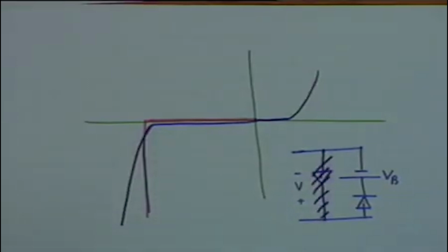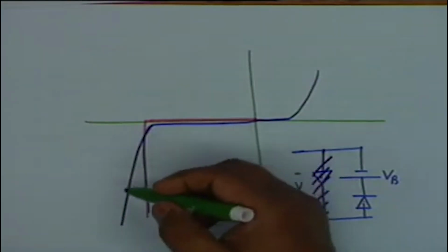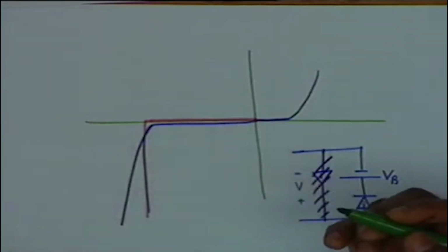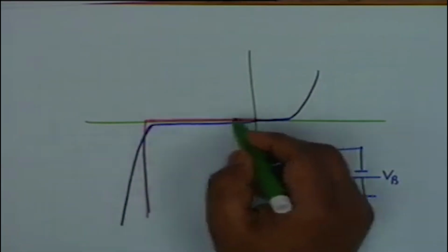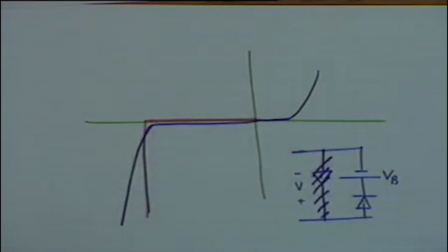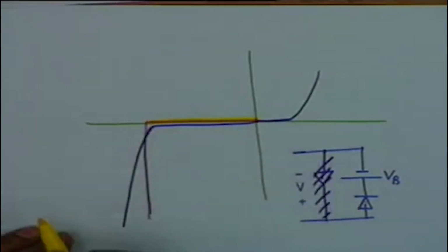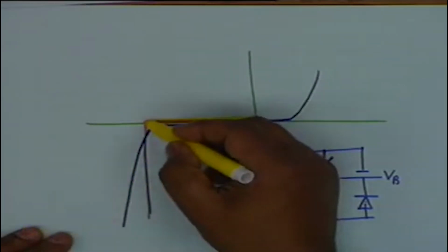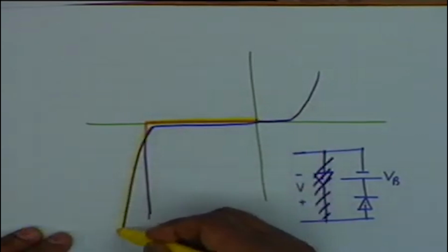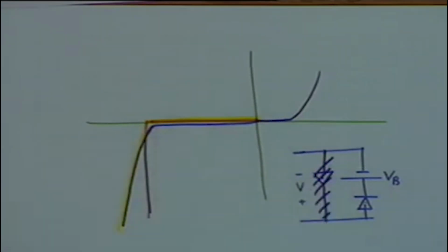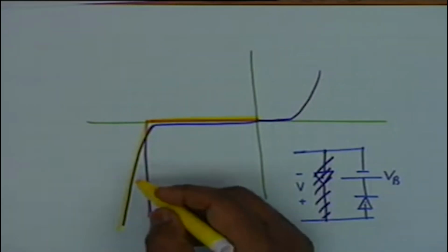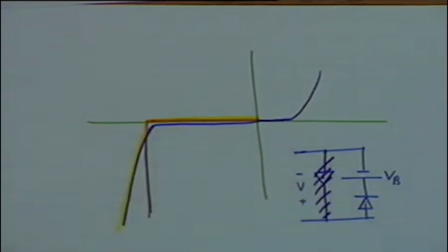Now, once again, the sloping character of the actual Zener diode can be approximated by including a resistance, and therefore what we do, I should use some other color, let's use yellow, is approximate up to this, the yellow line, and then we approximate by a straight line whose angle with this axis is slightly less than 90 degrees, and you can define a dynamic resistance for this characteristic.